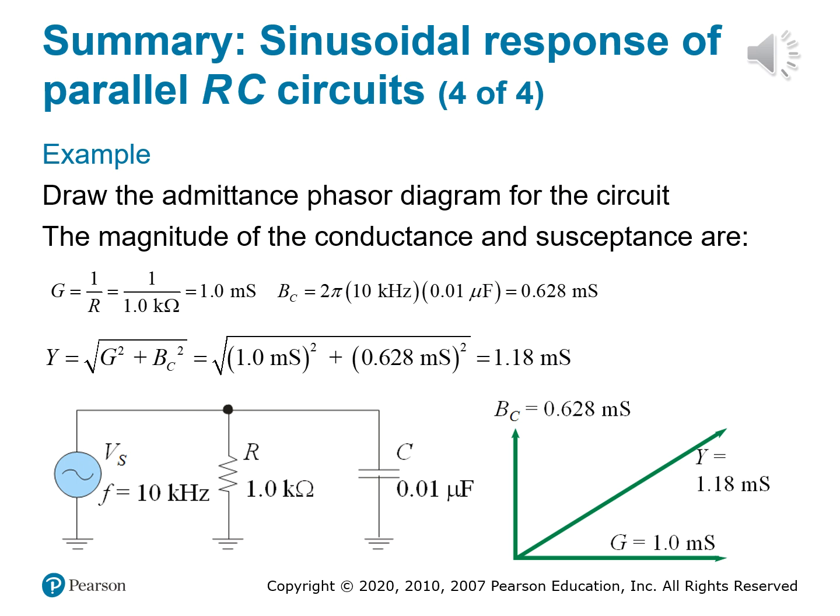So the admittance phasor diagram places G on the real axis, B sub C, the susceptance, on the imaginary, and Y is that diagonal. This triangle is going to let us visualize how current flows in this particular circuit. Remember that the larger the susceptance, the more the circuit behaves like a capacitor, because we're dealing with capacitor susceptance here. You might remember this triangle looking very, very familiar.